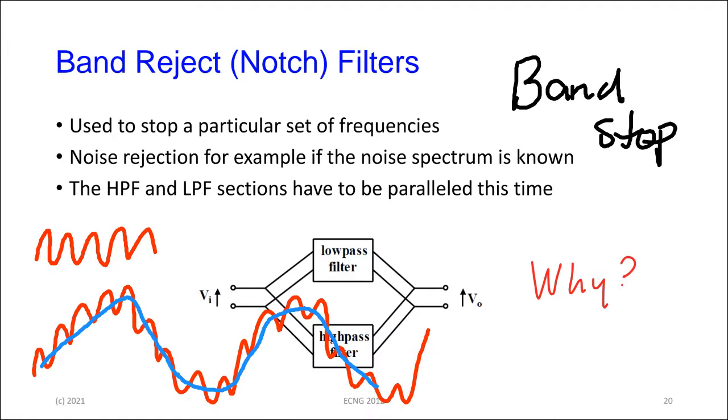We had mentioned one or two about the feedback noise that you hear sometimes with auditorium and public address system speakers. Those are automatic notch filters. They're either automatic or manual. The automatic one looks for the particular frequency that is causing the feedback to occur, and it creates a filter automatically at that frequency and removes that from the sound signal temporarily.